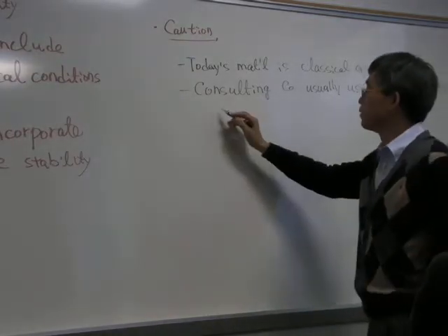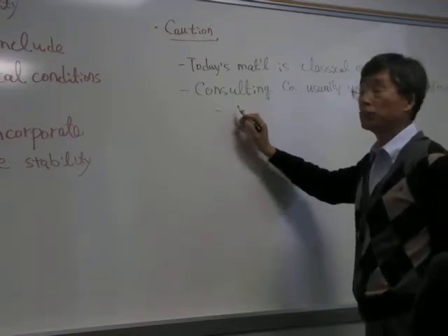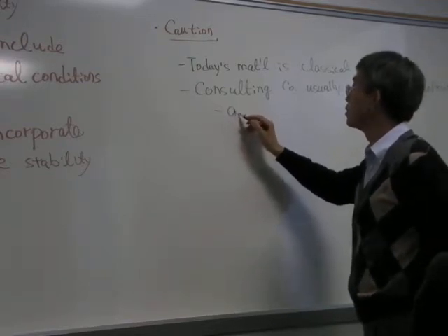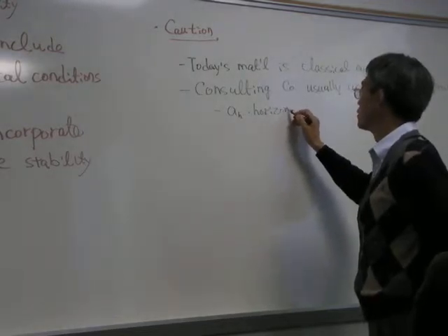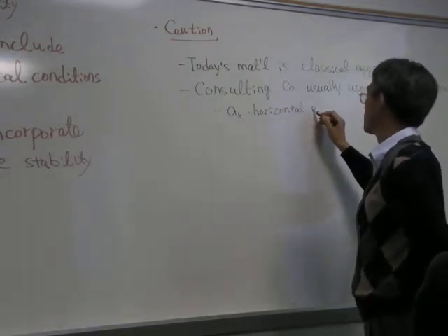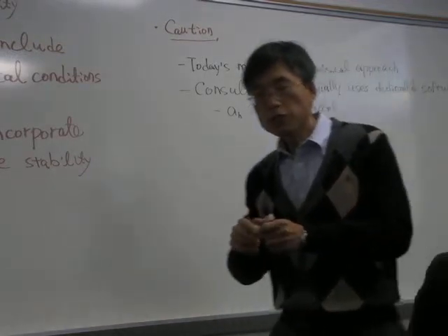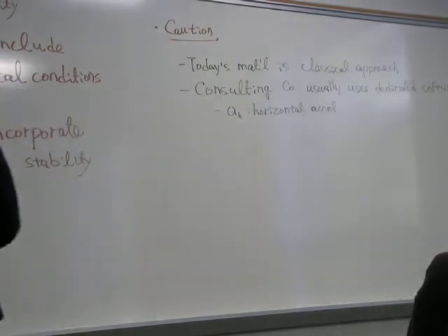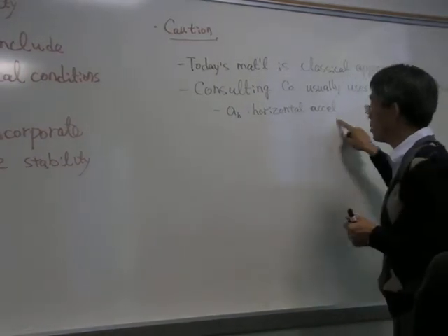Those softwares will typically need an additional input, so-called horizontal acceleration. It will require typical input like the cohesion, internal friction angle, thickness of the layers, height and slope of the slope, but it will require an additional one.